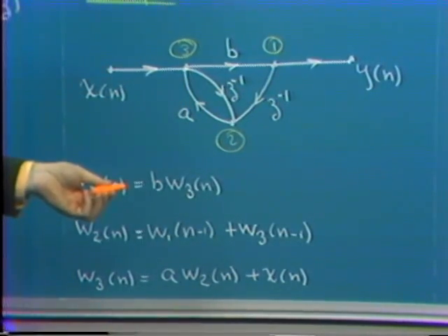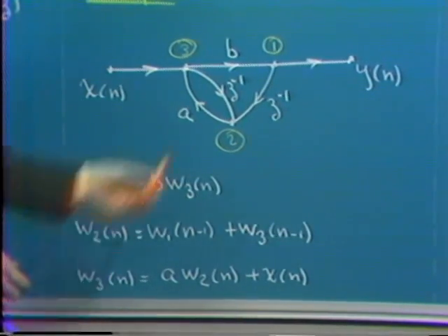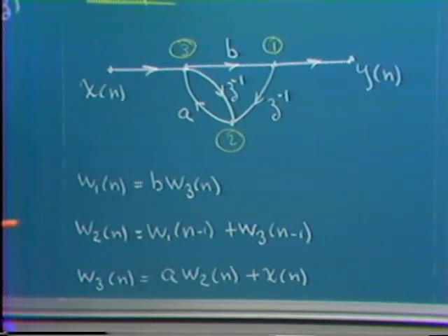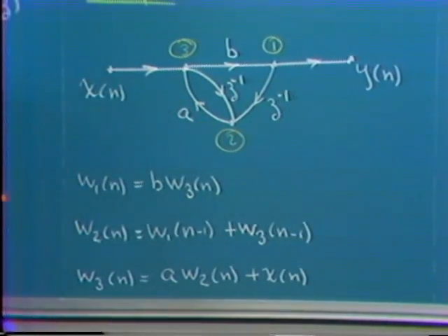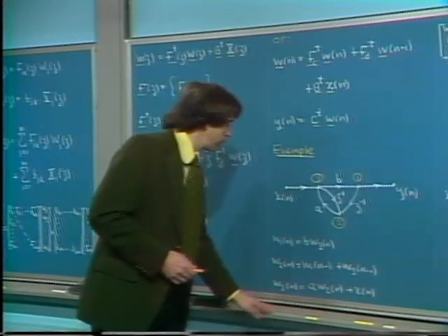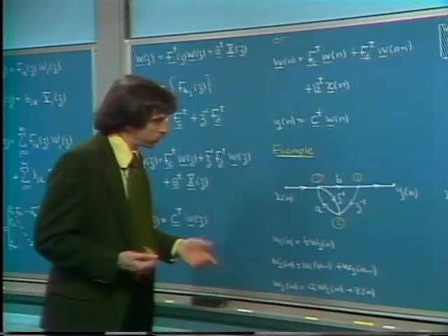And I don't have node 3 if I'm going to compute that after node 1. So actually, the order that I've specified here for the nodes is not an order in which I can compute the network, or another way to say that is that this network, as I've numbered the nodes, is not computable. But let's go on, and we'll look, in fact, at a rearrangement of the nodes that is computable.